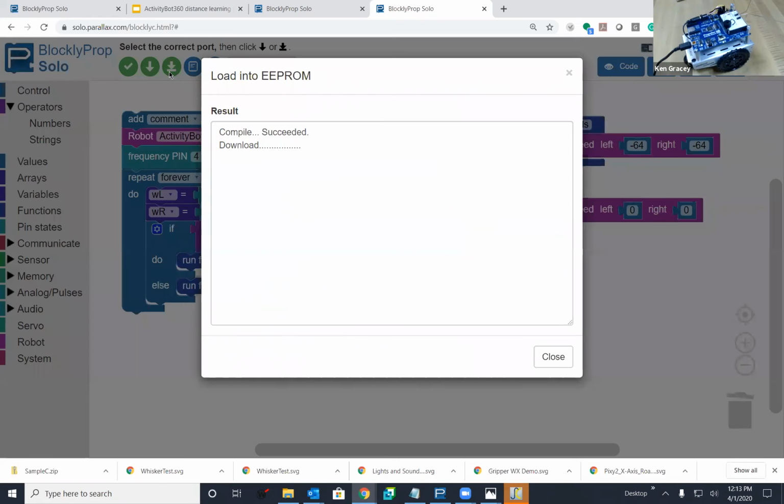And the program downloads, but the motors cannot be powered because the switch is in position 1. So I like to come to the robot, undo the cable, and then put the switch in position 2. If you had a program that already had some drive routines, they would have already run without signals to the motors or without power to the motors.